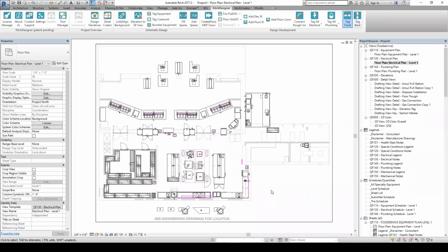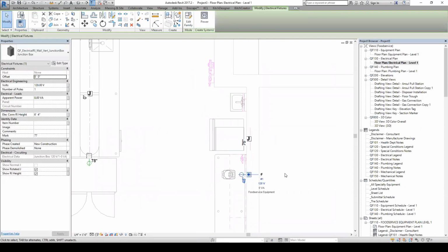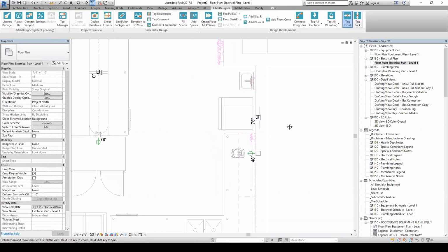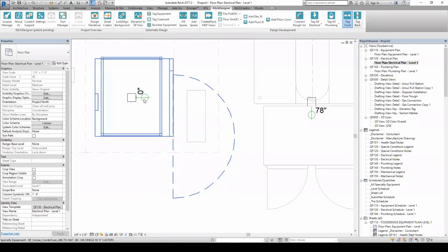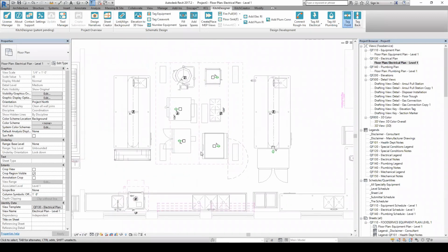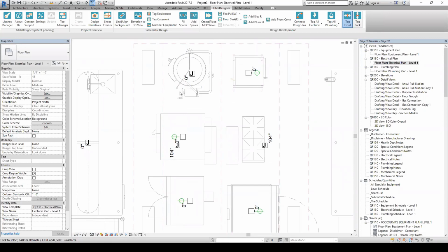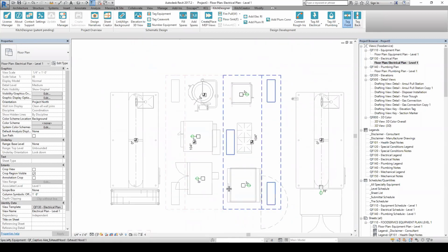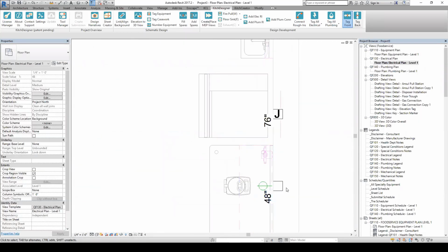So we can press OK, and if we zoom in, you can see some of our roughins here. Junction box, this is a single receptacle. These are stub up receptacles, stub up junction boxes. The location that it's placing these roughins is dependent on your settings. Wall roughins are usually set up to be placed in a wall if the equipment is within, I have it set up to be 30 inches from a wall, but you can change that dimension.